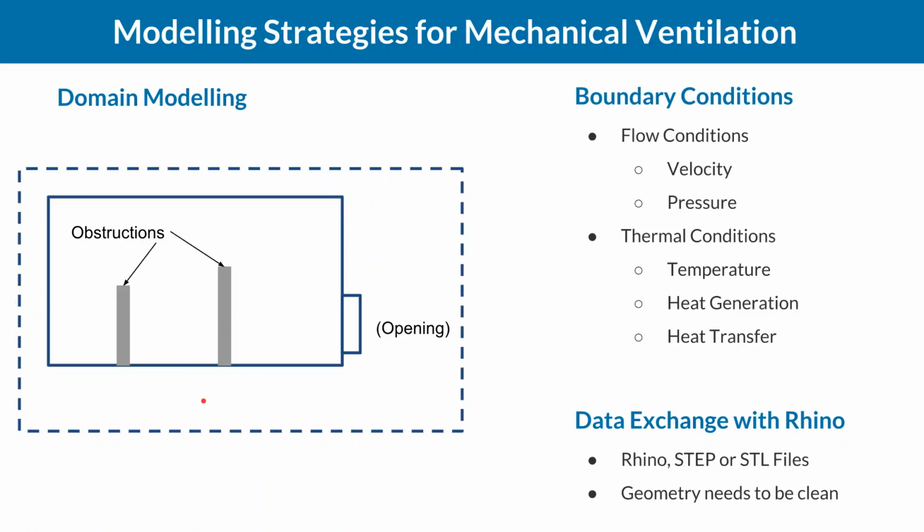And another big difference is related to your CAD model. If you want to include the external flow, you also have to make sure that the walls of your model have a defined thickness. Otherwise, it can cause some problems. And for sure, you can also combine both, even if you want to combine everything, so that you consider temperature, internal flow, and external flow.